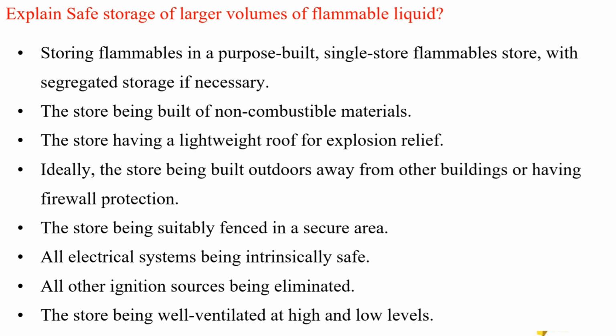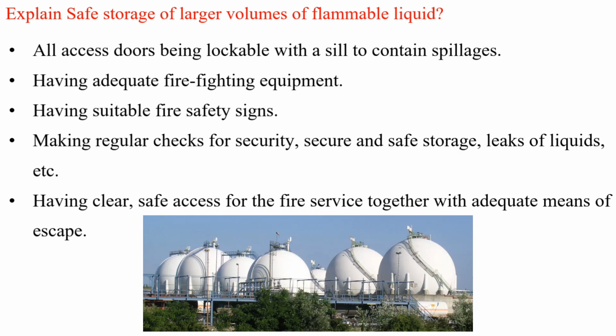All electrical systems being intrinsically safe. All other ignition sources being eliminated. The store being well ventilated at high and low levels. All access doors being lockable with a sill to contain spillages. Having adequate fire-fighting equipment. Having suitable fire safety signs. Making regular checks for security, secure and safe storage, leaks of liquids, etc. Having clear, safe access for the fire service together with adequate means of escape.